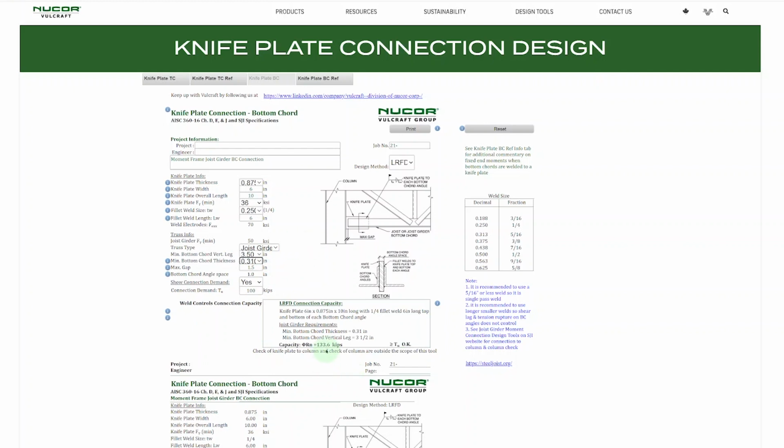So now I'm well over the 100 kips that I'm looking for. So if I start backing down that weld length, so 111 kips, now I'm too low at 89 kips, so I'll put that back at 5 inches. Maybe I can fine tune that a little bit more. But now I'm saving maybe a little over an inch of weld. It's a slightly larger weld size.